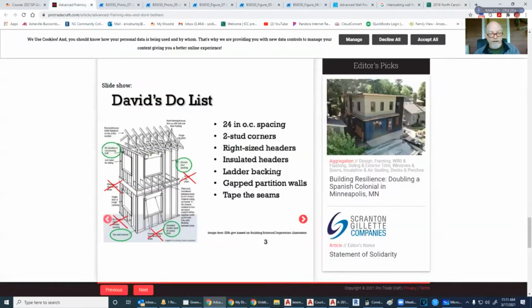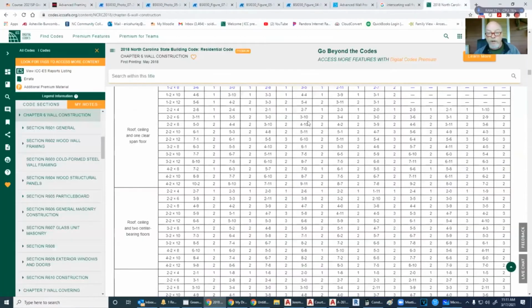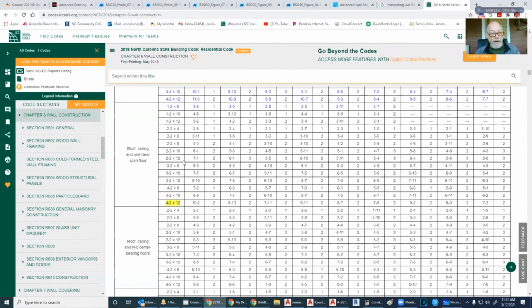Now, once you figure out what those are, you want to insulate the crap out of them. Basically, I try to go with the least that I can. Down here, I've got 4 2x12s and I can go for a longer span. But if I'm using 4 2x12s and a 2x4 wall, that's going to be wider than my wall, so there's nothing there to insulate. I'm going to have a cold spot that allows heat transfer to cross through there. Whereas if I'm doing smaller spans and I can get by with 2 2x12s, then I have a little bit of space to put some insulation in there to eliminate that movement of heat.